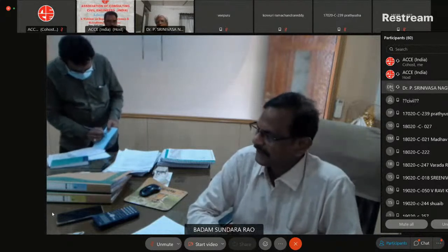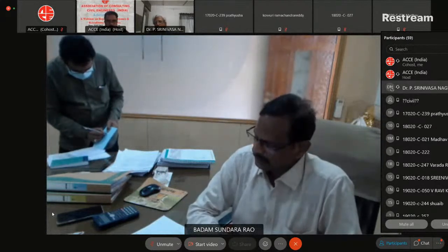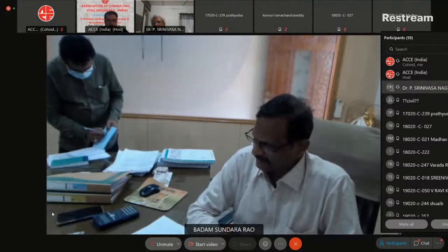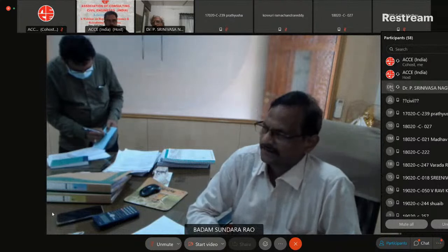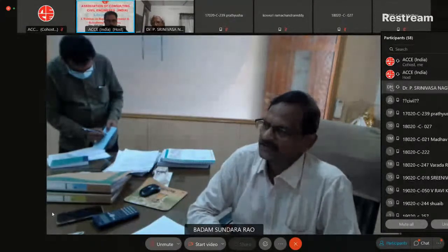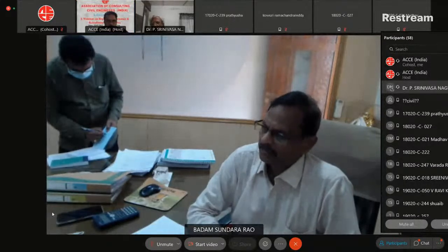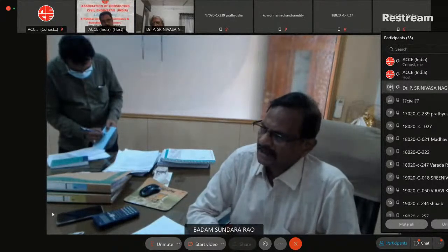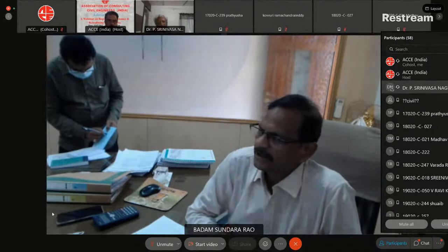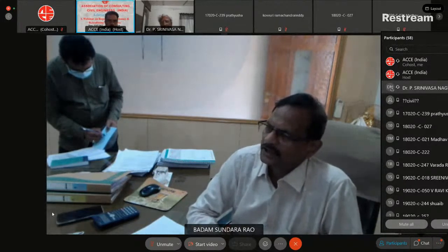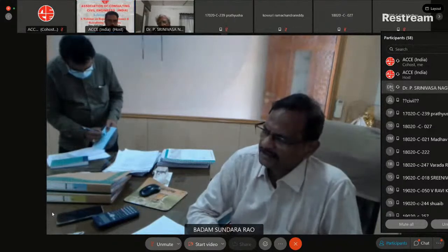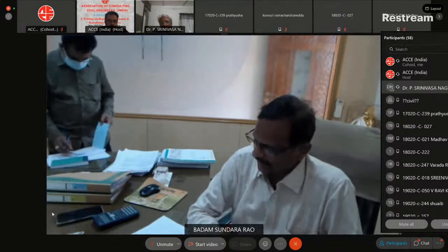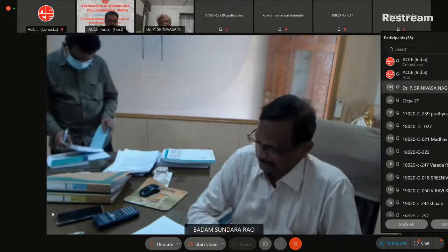While doing basement filling, one must be very careful in using soils without high swell index. If the soils have a high swell index, it will definitely affect the quality of brick masonry, which may lead to cracks, and the structure looks very odd. I explained the same thing in earlier webinars. JNTU Anantapur campus at Pulivendula is the best example of high swell soil used in the basement.